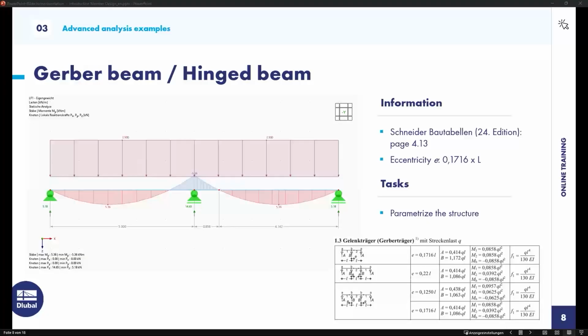And if you place that connection in the spot of the bending moment being 0, then you can simplify that connection by far. So this is a clever way of splitting beams in a good way, let's say.